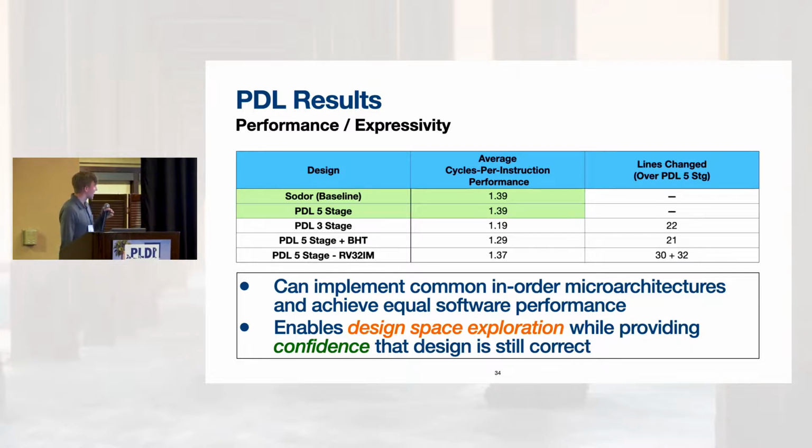And the kinds of changes you're making are like adding or removing a stage separator, maybe merging two if statements together. So really, it looks like 4 lines of code change, but your logic didn't change very much. And so it makes it quite easy to explore designs with different trade-offs that would be very hard to do in RTL, because you'd have to think very carefully about all of this control logic that detects data hazards, that fixes up speculation, et cetera.